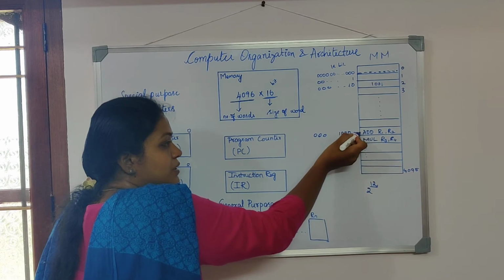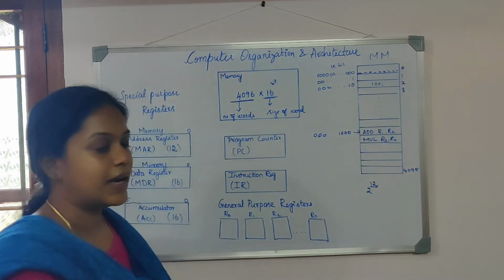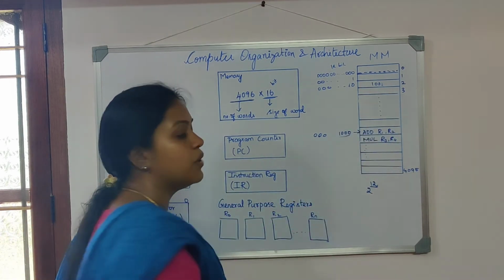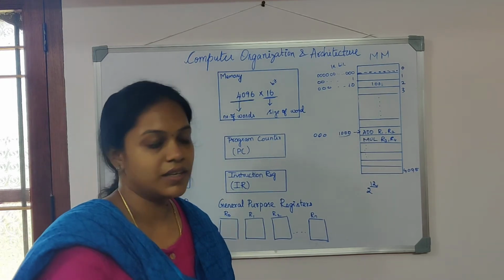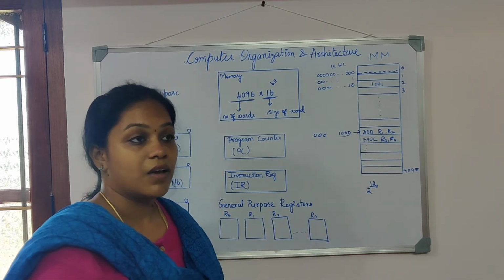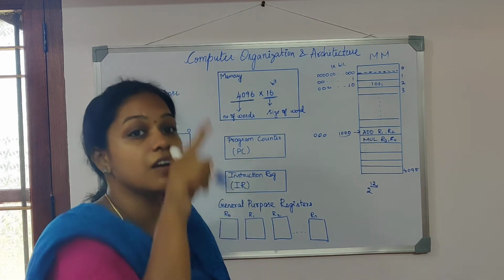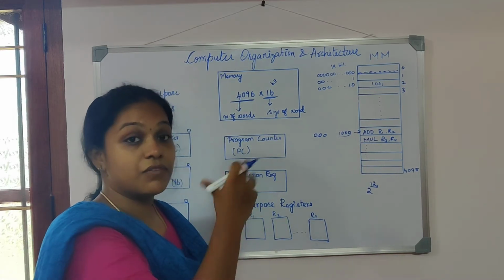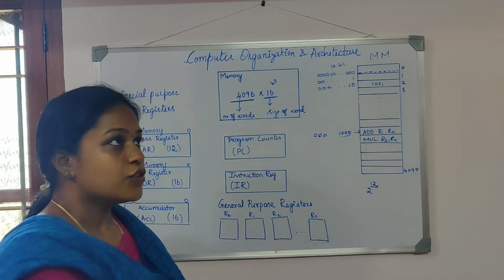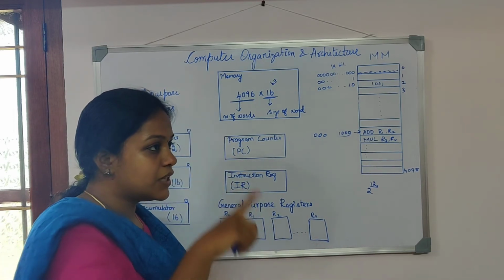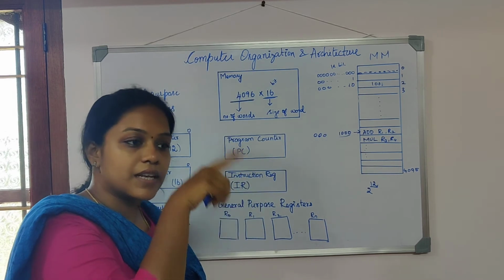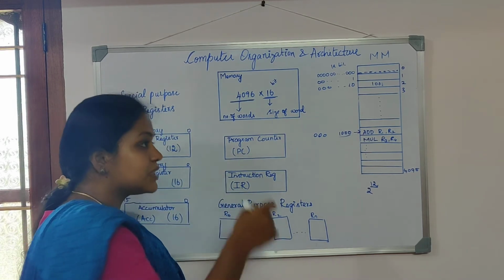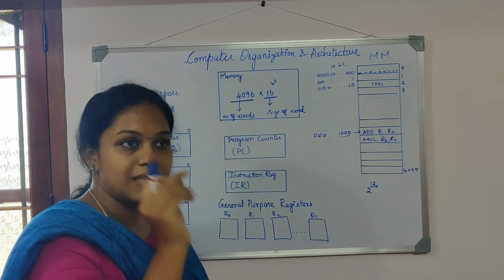Now I am executing this instruction, say add R1, R2, which I have to pick from the address 1000. The 1000 address holds the instruction, add R1 and R2, and the processor will execute that instruction. Then it has to move on automatically to the next instruction, pick it, and give it to the processor for execution. This has to be done in a serial manner: first instruction executed, then the next, then the next in sequential order. This program counter solely serves this purpose.